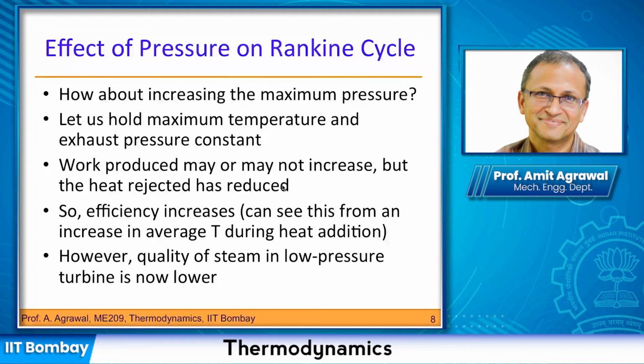So the statement that we are making is about the work done. We are not looking at it from the point of view of heat added, we are looking at it from the point of view of work which is being done. If you compare the two areas, they turn out to be reasonably similar. So that's how you can say that the work being done in the two cycles is similar. And then, as you said, the heat rejection is definitely lower in one case, and wherever it is lower, the overall efficiency is going to be larger.